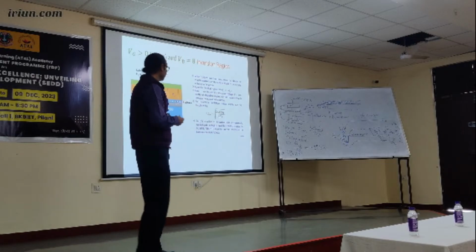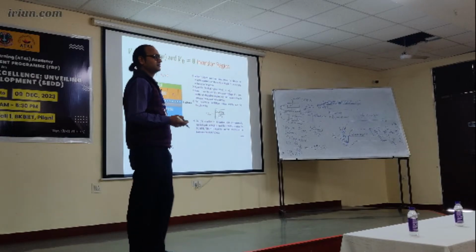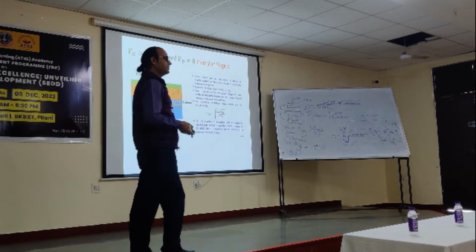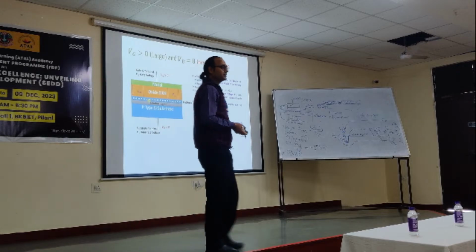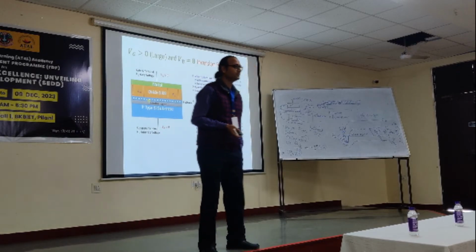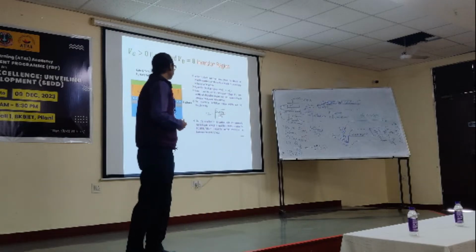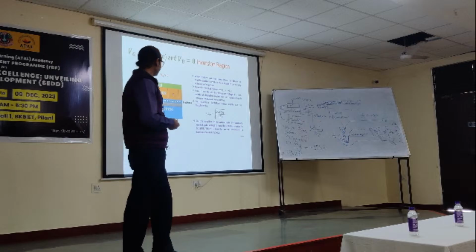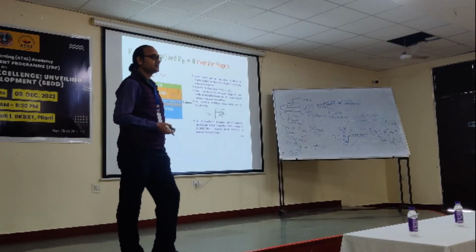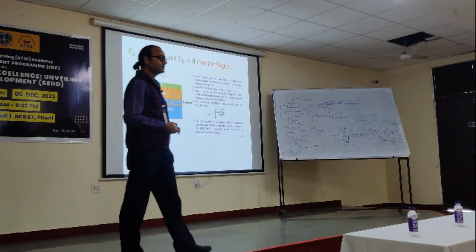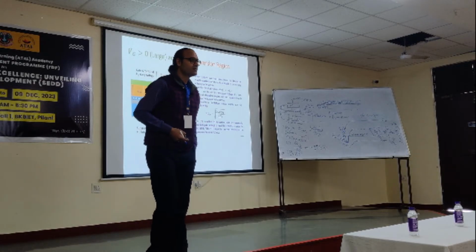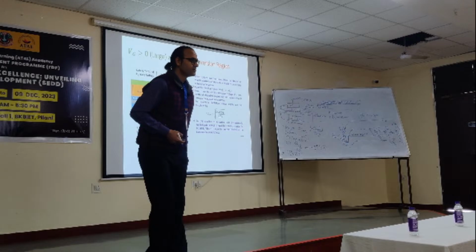Because the mobility of holes is very less in comparison to electrons. In case of silicon, it is around 1/3 as compared to electrons. So current flows due to the electrons only, as far as current flow is concerned. So the number of electrons are reduced due to the recombination process in the depletion mode?